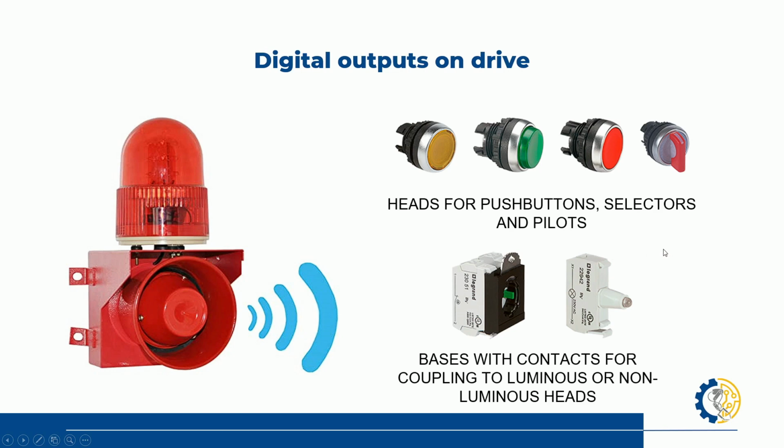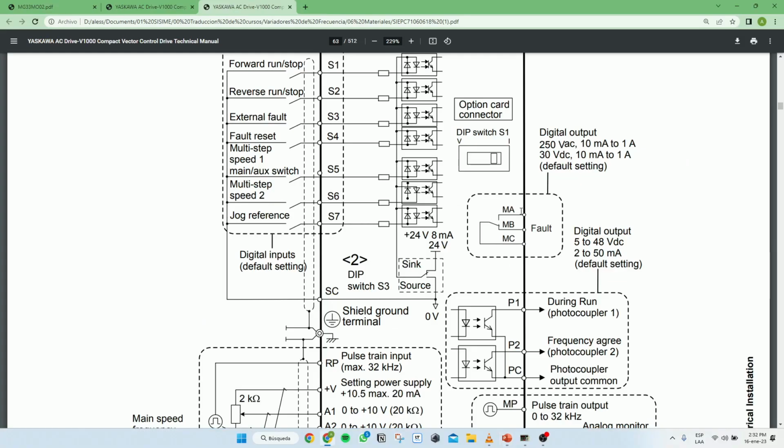So now, our phase I'm going to connect in DC. But my neutral is the one that I'm going to connect over on this side. I'm going to take my neutral directly and connect it to my MC, which is my common.